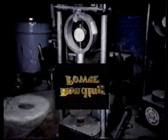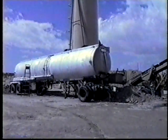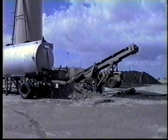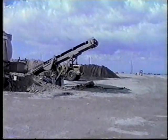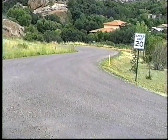A road department with their own pavement materials testing lab ran Marshall test mix designs using road oil as the binder for treatment of their reclaimed asphalt pavement millings. While they were able to achieve pavement surface stability suitable for heavy traffic in their lab testing at relatively low road oil treatment rates, they chose to push the limits of the resin-modified binder when it came time for field construction by using an even lighter application rate, as if they were going to use the treated mixture for base